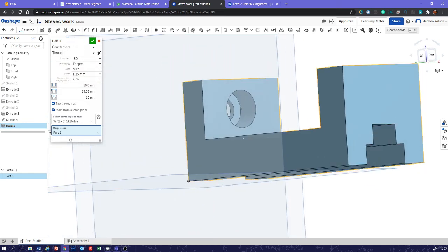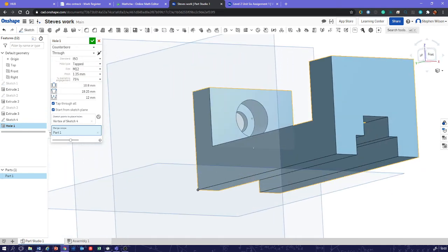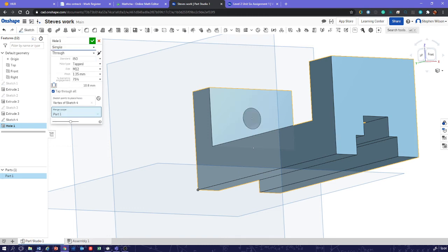I'm just going to click select our original part there. Right. So can you see there we chose a counter bore hole. So that's got a hole with straight sides. I'm sure I've said all this before. Okay. A countersink has sloped or tapered sides, and that lets different types of screws just sit flush with the surface. We don't want that, we just want a simple hole. Okay, we're going to say a through hole. Blind lets us specify the depth, and blind in last lets us specify the depth in the last section.